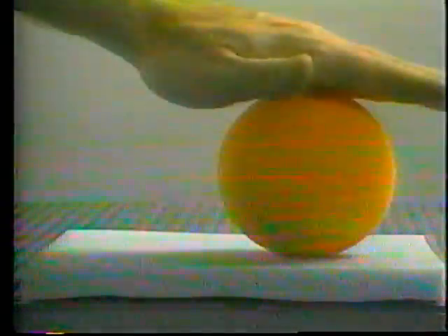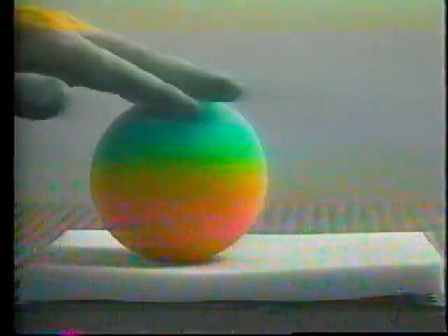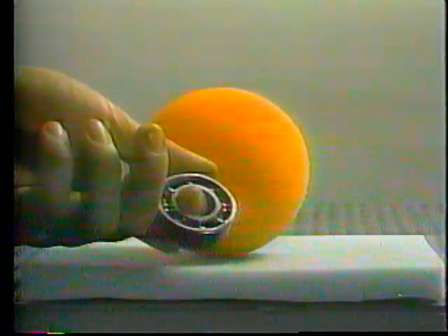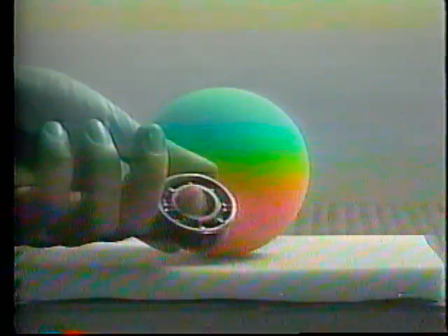In some cases, the actual amount of surface area contact between metal parts is small. This ball bearing, for example, has very little surface area contact and normally produces very little friction. However, the rolling action is not quite perfect, especially when the bearing is heavily loaded or if the balls or rollers are distorted. A thin lubrication film is still essential to separate the parts.